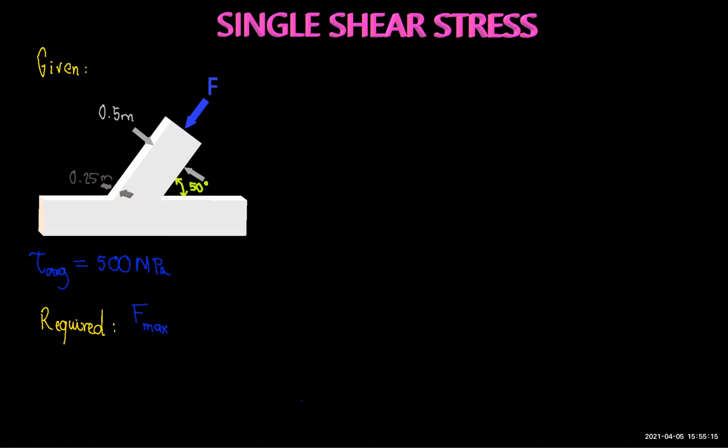In this problem, our point of focus should be at the point of contact between the horizontal member and the supporting strut. So, the first step in the solution will be to make a cut at the contact point. This is with the purpose of analyzing the internal loading in the inclined member.